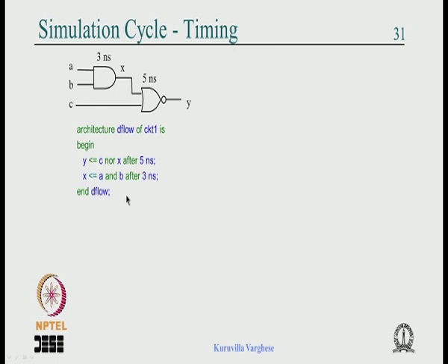So, systematically, whenever there is an event on a particular signal, the simulator looks at the right hand side of the assignment, and you can view this as something like a sensitivity list in a process. So if an event happens on A at 100 nanosecond, X will get an assignment at 103 nanosecond. So at 100 nanosecond, once all the computations are over, the simulation time is moved to the next event, that is 103 nanosecond. So look for X on the right hand side, then X comes here.